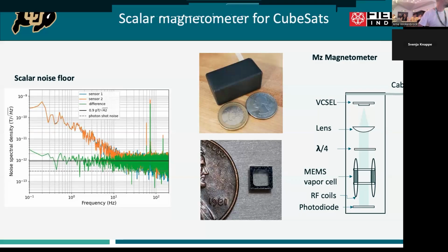The shield? Well, in the application, I don't want the shield. When I put it on the satellite, I don't want any shield, I want to measure it. It's just in my lab, in order to assess what my magnetometer can do, I put it inside a shield, because otherwise all I'm measuring is that cell phone and the car driving by. I need a contained environment that is controlled enough that I can actually see what my magnetometer is doing. And so that's when I use the shield.